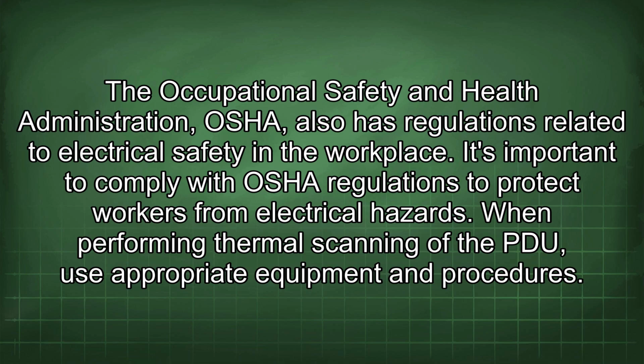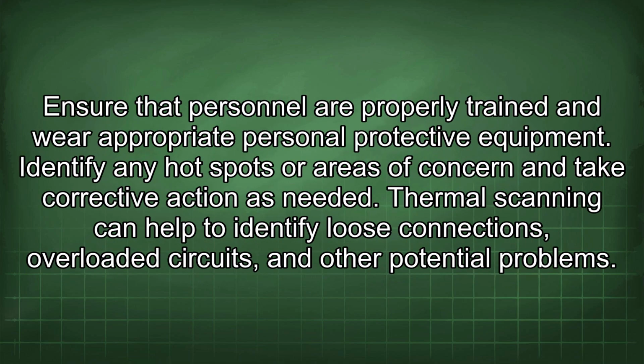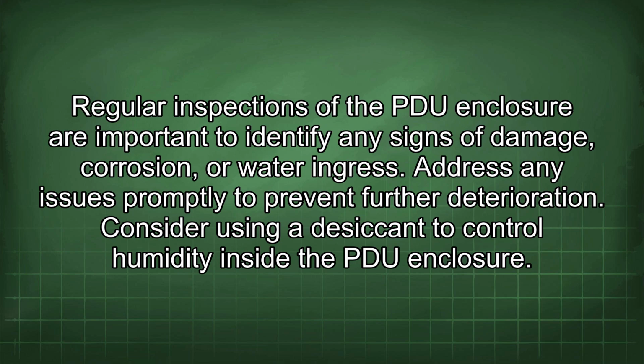When performing thermal scanning of the PDU, use appropriate equipment and procedures. Ensure that personnel are properly trained and wear appropriate personal protective equipment. Identify any hotspots or areas of concern and take corrective action as needed. Thermal scanning can help to identify loose connections, overloaded circuits, and other potential problems. Regular inspections of the PDU enclosure are important to identify any signs of damage, corrosion, or water ingress. Address any issues promptly to prevent further deterioration.